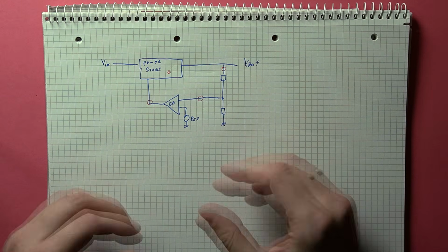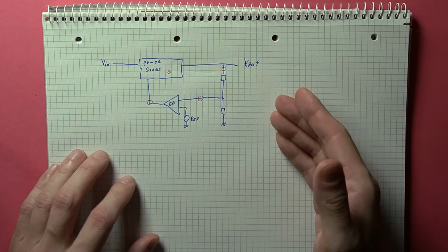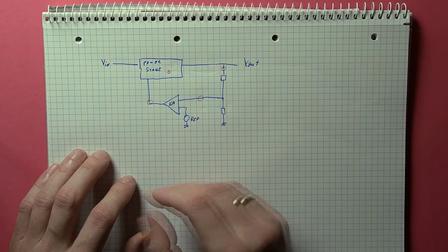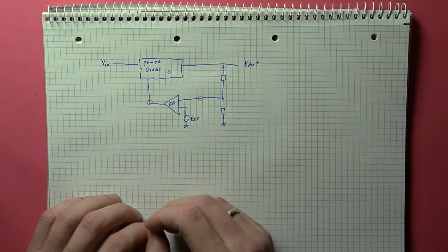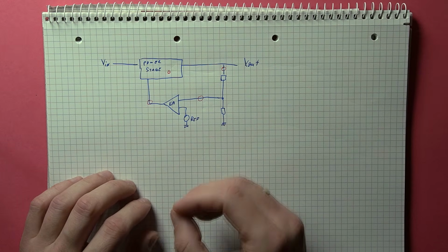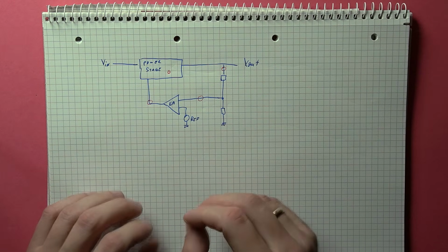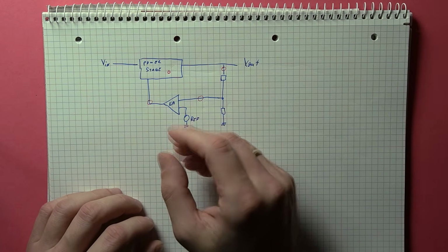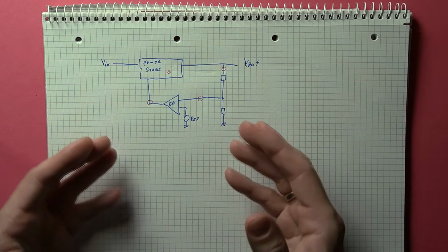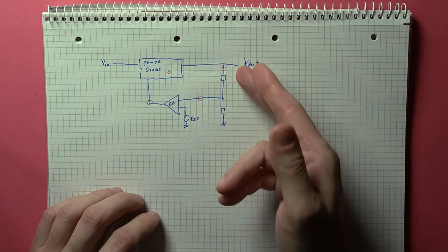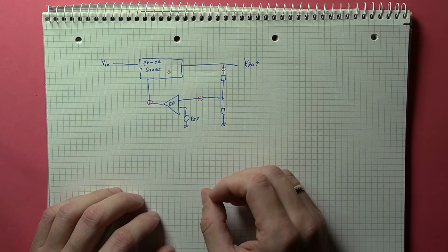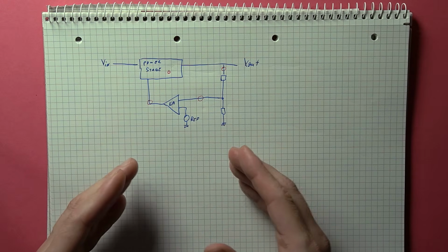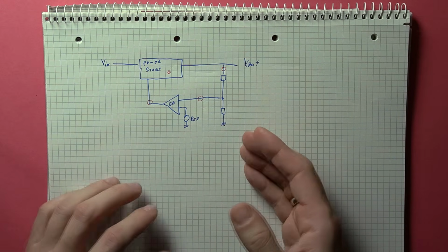First and foremost, the breakpoint needs to be accessible. In most cases, the error amplifier output is integrated, so that won't do. Next, the point needs to be in a linearly behaving part of the circuit, so you don't really want to interrupt the gate of a switching converter. So this usually leaves the feedback resistors as the only access point. But even here, we need to make sure that the measurement does not affect the overall behavior of the supply.